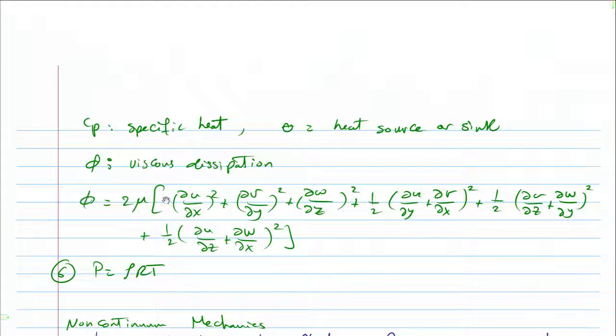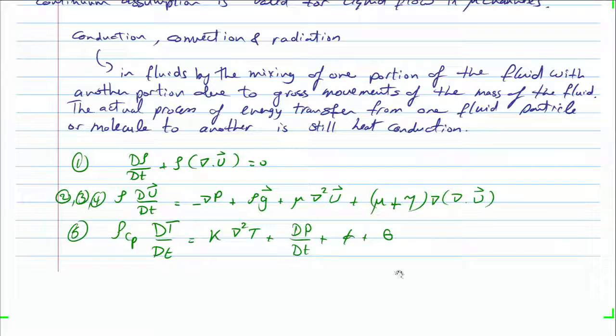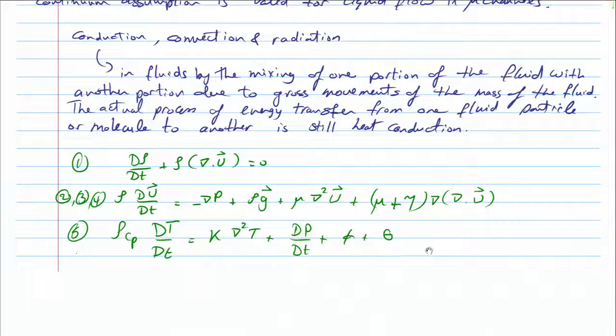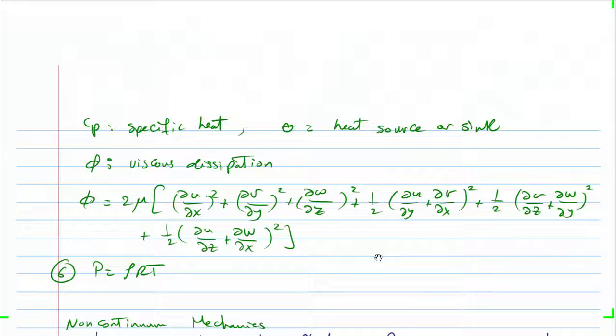So now this is the long viscous dissipation term. When you look at this term, this is basically all the work done by the friction, the viscosity, translating into a source for energy. Because of the squares, this term will never produce a negative sign, meaning that in the energy equation, the friction will never make you get cooler. It will always make the fluid get hotter. All right? Hence the name viscous dissipation.